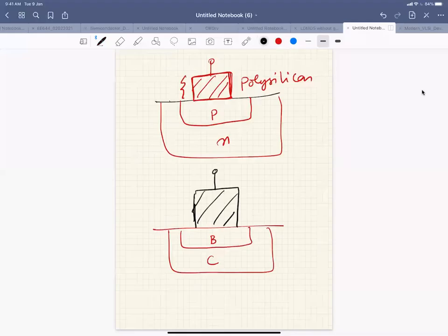because this is normally done by CVD, or you could also do it by epitaxy. So during this deposition process you could also dope the emitter, right? This is called the polysilicon emitter, right? And the polysilicon emitter is very common in modern bipolar transistors, because once you have the emitter defined by deposition, then